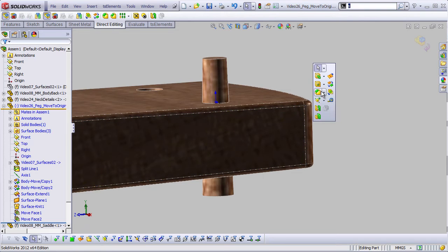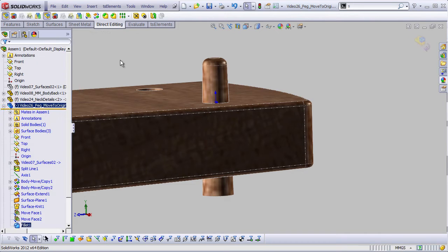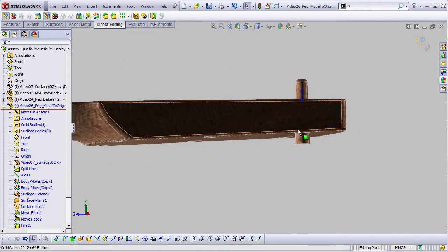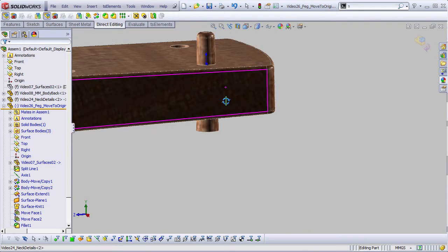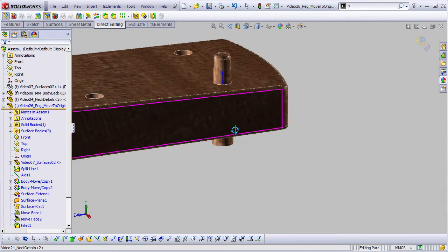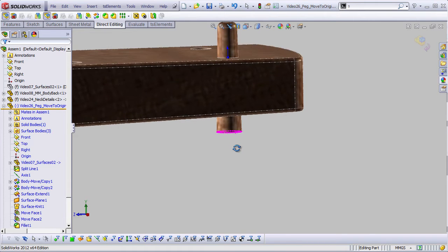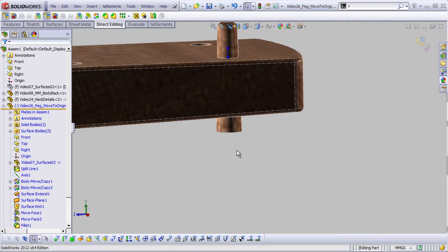We can also grab our round tool. I could round this corner by, let's say, 1.5 millimeters. That looks pretty good, so it's nice and rounded. All right, looks good. And finally, we're going to want to add the key at the bottom of this for turning it. And there are all kinds of ways that you could decide you want to do this. I find I like to do this in quarters. I just think it's the simplest, cleanest way to do it.